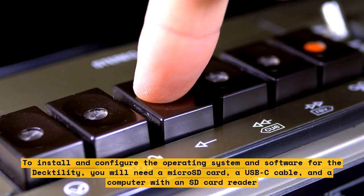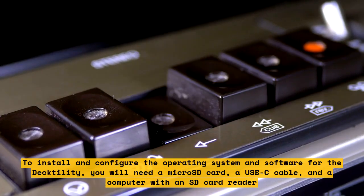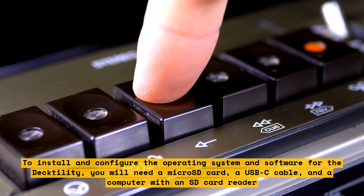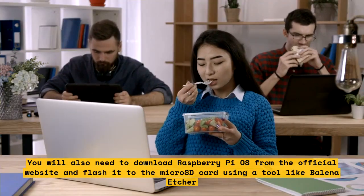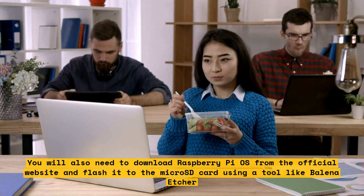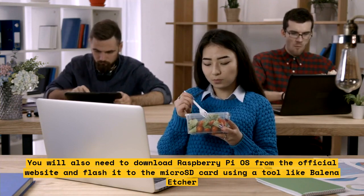To install and configure the operating system and software for the Decktility, you will need a micro SD card, a USB-C cable, and a computer with an SD card reader. You will also need to download Raspberry Pi OS from the official website and flash it to the micro SD card using a tool like Balena Etcher.